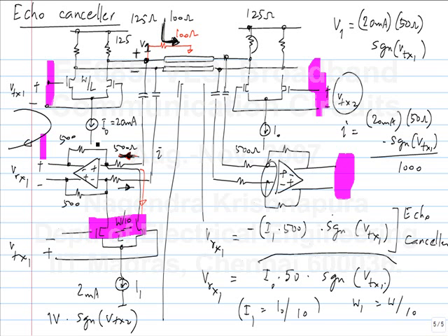Yeah, that's true, and that can be made sure of. I didn't show any details of the op-amp, like I have not said what is the common mode voltage of the op-amp, but we can adjust it so that it is the same. And if it's not the same, there will be some mismatch because of that as well. So firstly there will be random mismatch because you can't just match two circuits exactly, and some systematic mismatch maybe because you couldn't match the bias conditions exactly.